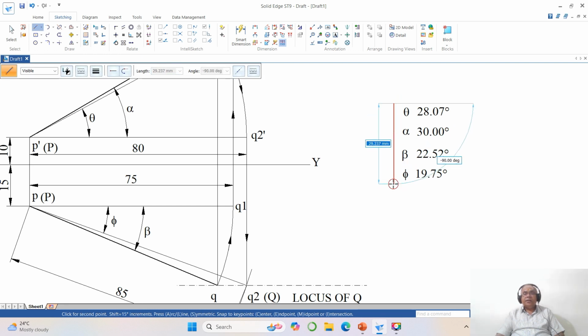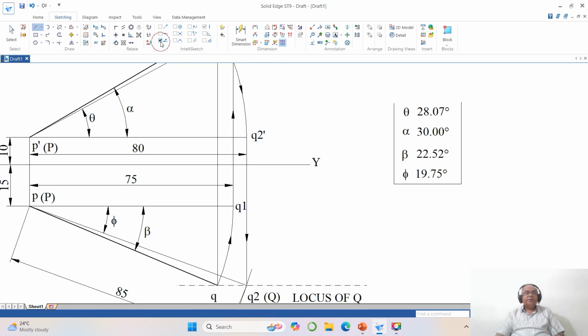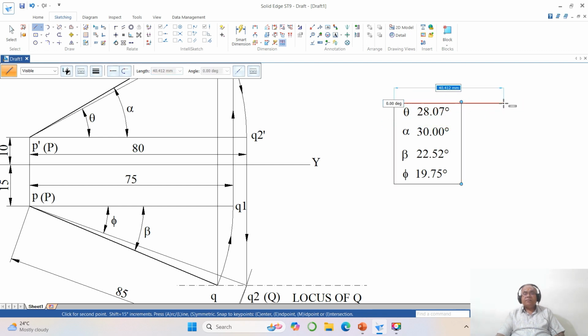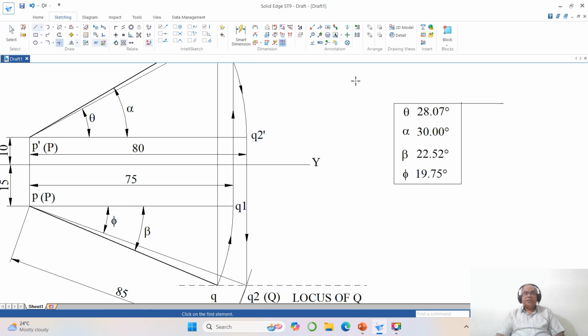Draw one vertical line and then draw one more horizontal line. Then you go to line, take endpoint. If you don't have endpoint here, you just go to endpoint, select this and draw a horizontal line. And then go to trim corner between these two. Then go to move, enable copy, you take this, right click. I don't want the displacement along the x direction, so you keep x as 0. So now you're going to get y like this. This is the advantage of doing that.